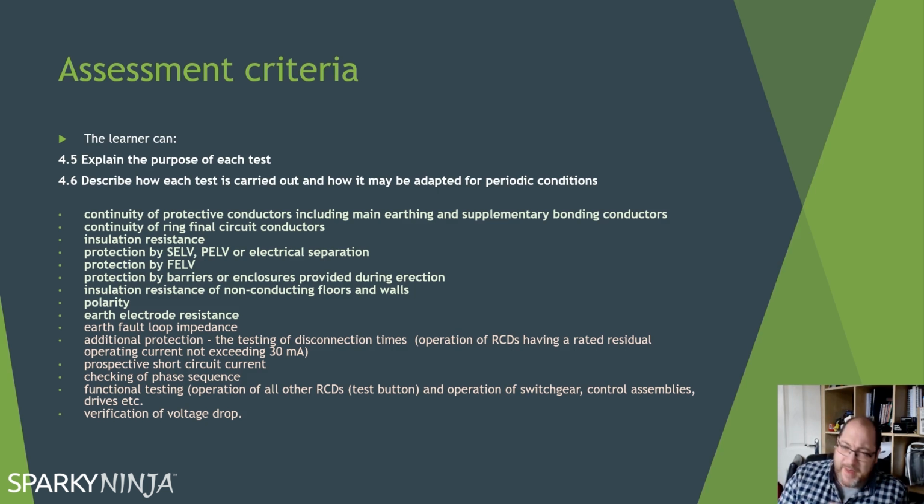Going down a more detailed route, you may need to consider things like protective conductor currents and filtering if you go between live and earth. You may get some feedback. But again, it all depends on your knowledge of the equipment that is in the circuit. But yes, insulation resistance on a new install must be done. On a periodic, I'd like it to be done, but I often see that it's just limited. What I'm also seeing is it being limited or being ignored, but contractors will still put greater than 200 or greater than 999 because that's what they've always seen, which is a bit of a concern.